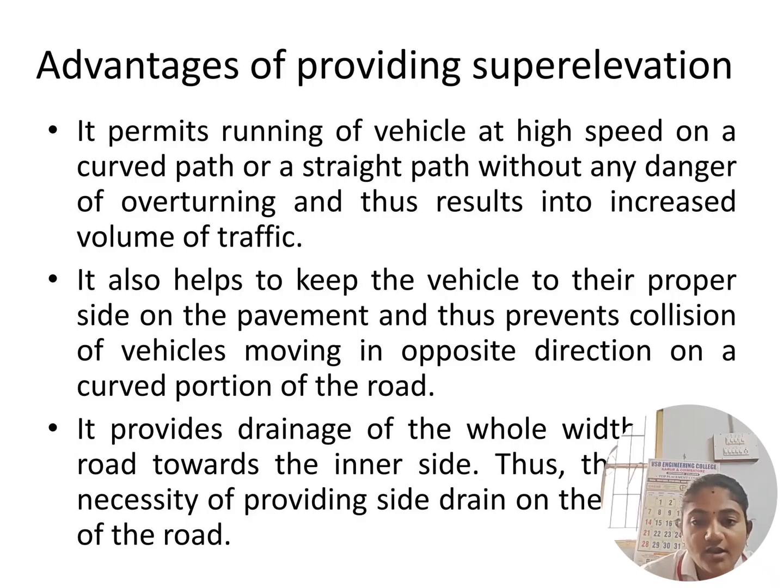Advantages of providing a super elevation. It permits running of the vehicle at high speed on a curved path without any danger of overturning, and it results in increased volume of traffic. It also keeps the vehicles to their proper side of the pavement and prevents collision of vehicles on a curved portion of the road. It provides drainage of the whole width of the road towards the inner side, which is highly important.